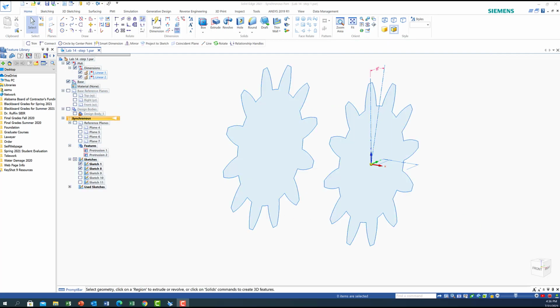Once we finish with the rotation, what I'm going to do is bring back the original sketch and the rotated sketch. So this is the front of the helical gear, and this is the back of the helical gear. So what we're going to do, we're going to connect them. We're going to use the Loft command. So we're going to go to Loft and connect, say okay, so it's going to be this one.